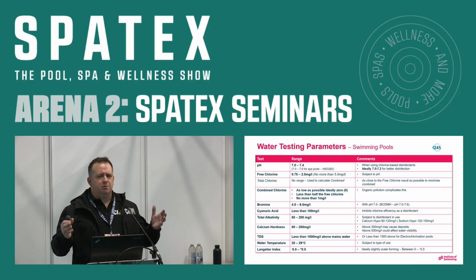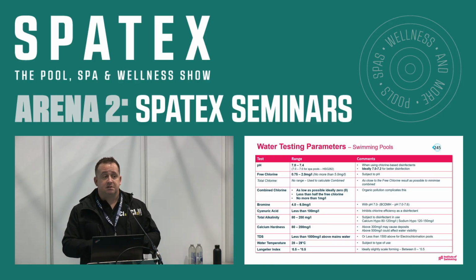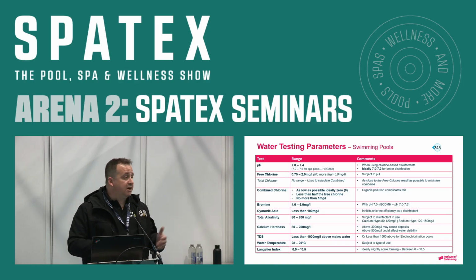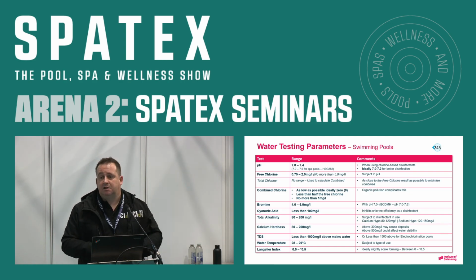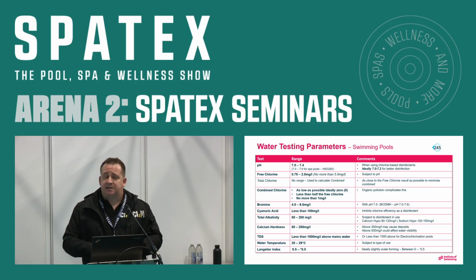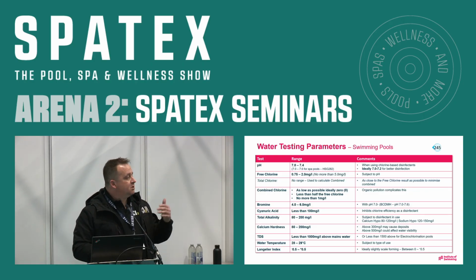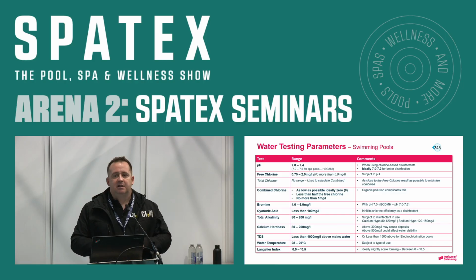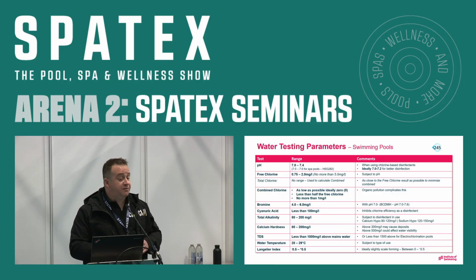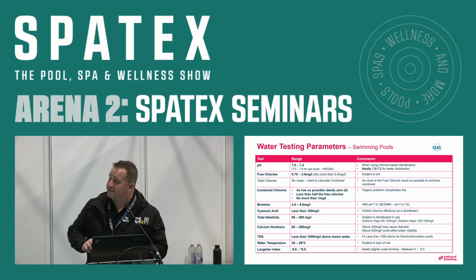Okay, bromine. Anyone use bromine? No, you don't see it very often. You may see it in hot tubs more than anything else. Again, a slightly higher level. Bromine is a whole different kettle of fish when we start looking at chemistry. All right. Cyanuric acid, less than 100. And cyanuric acid, we work with outdoor pools. Try to make sure we keep that nice and low, because it will affect how your dose control units work if you start getting too far off. Okay. Alkalinity and calcium hardness, we'll talk about in just a second.